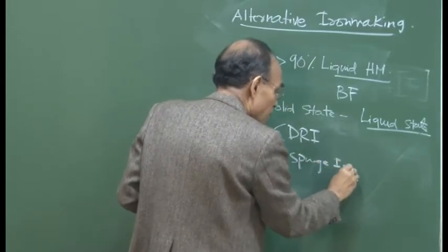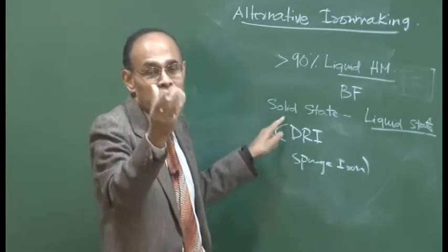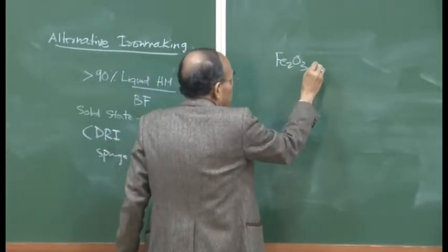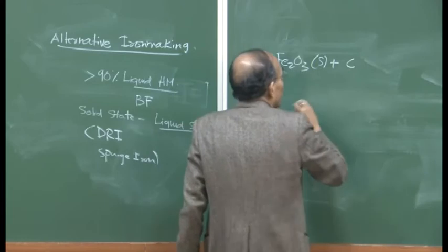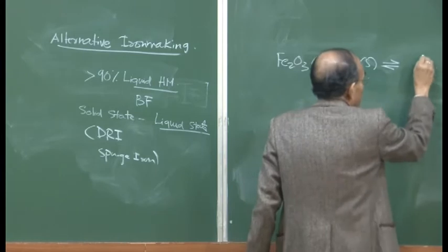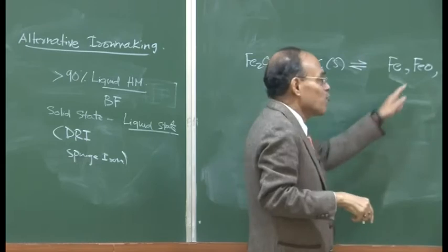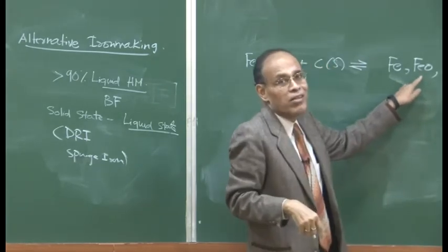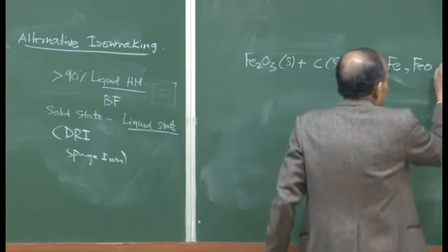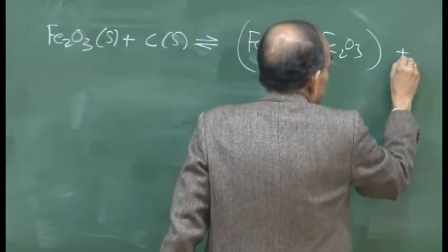And the name sponge iron comes because if you look under the microscope, these are partially reduced. So, you take hematite ore, for example, and if you use it solid and then reduce it, as I have also told you in the context of my discussion on blast furnace, you can get a mixture of Fe and FeO. I am still writing FeO for the sake of simplicity, and not 0.947, because now we are not doing stoichiometric calculations, and we can have a mixture of these.